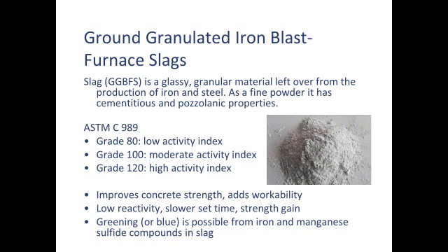It adds workability, which is why it's used. It can improve a lot of properties of concrete, but it's not very reactive as compared to metakaolin and silica fume. So you have slower set time, slower strength gains up front. Again, in the construction world, it doesn't matter, but for us it does matter. Perhaps one of the biggest reasons why I'm not a big fan of it is there's a definite greening effect.